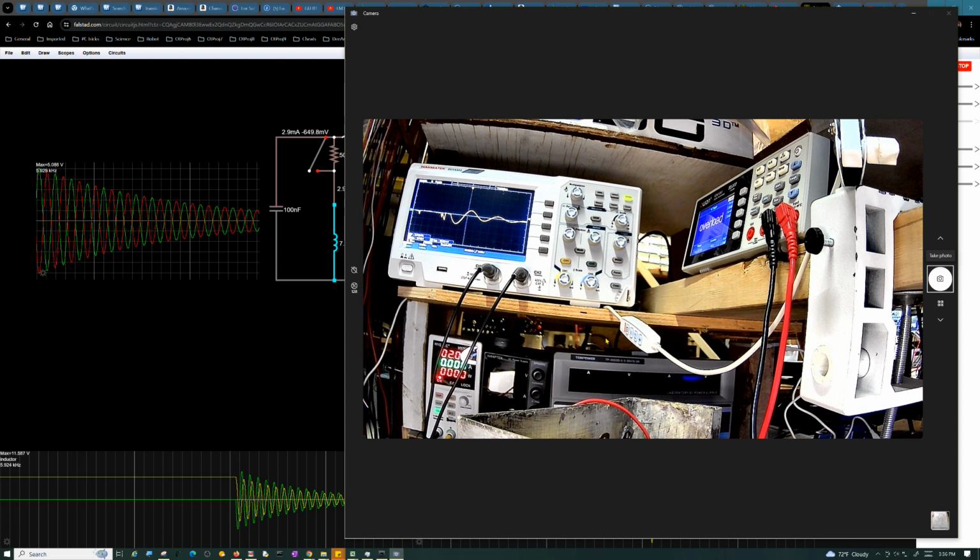Okay, this time we only got about 9.7 volts, but I got it set to 5 volts per division right now, so it's about 14 volts in practice. Let's try it again. Again, this is a really lossy core. You got to leave it on the full time. Nope, it's even less this time.